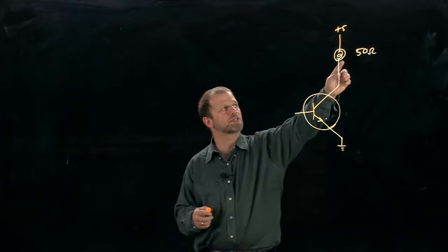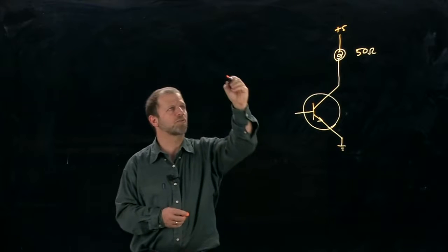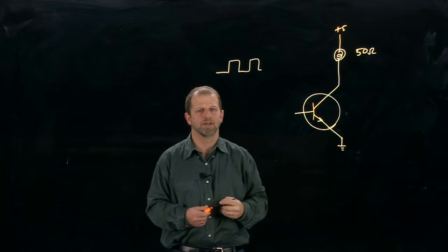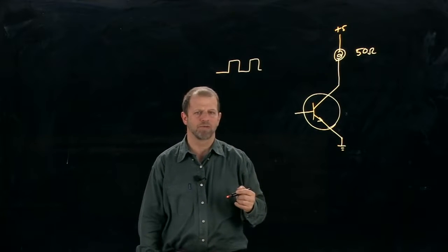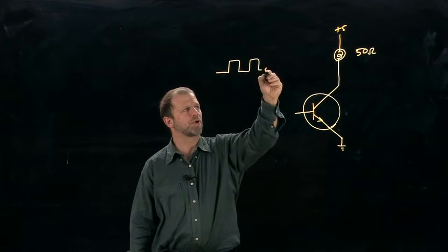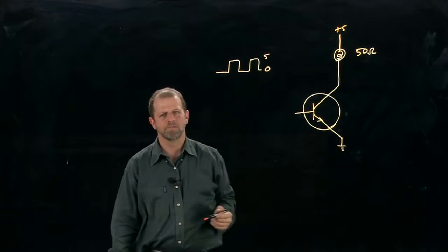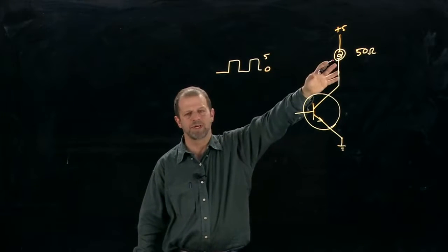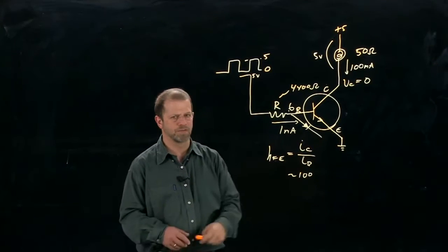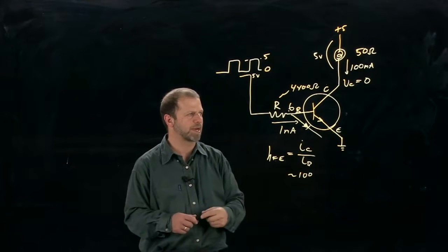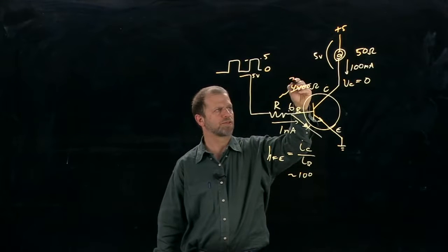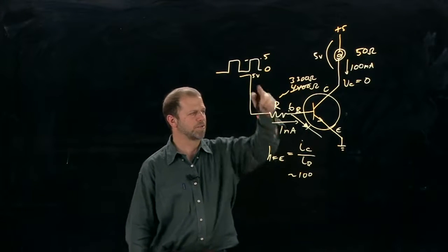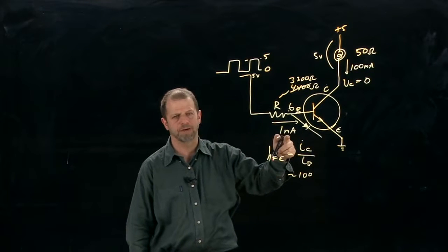And I'd like to turn this light bulb on and off as a consequence of a square wave train. So you're getting a signal from a function generator or from some other part of your circuitry that ranges from 0 to 5 volts, maybe with fairly high impedance so that you certainly can't use that to drive the light bulb directly. And then if the gain of the transistor is smaller than we expect, things are okay. So maybe I'll use a 3300 ohm resistor here, which happens to be one that I have. Now the base current is a little bigger than a milliamp.